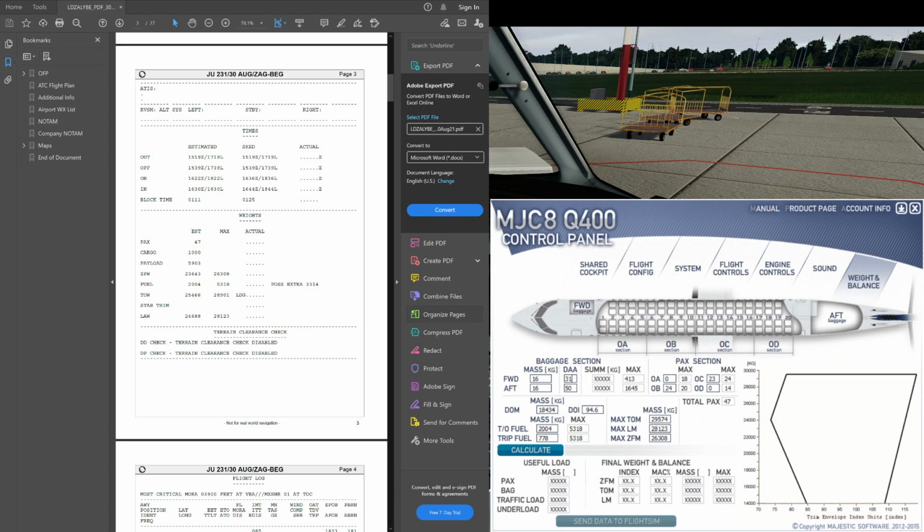And also because the bag weighs 16 kilograms and we have 1 ton of cargo, I'm just going to do a simple calculation and see. So it's 62 bags that we are going to need. 62 plus 47 bags of the passengers, it's 109 bags. 109, that means we can put 70 bags in the back or the aft compartment and 39 in the front.